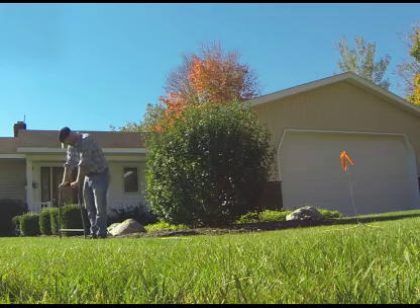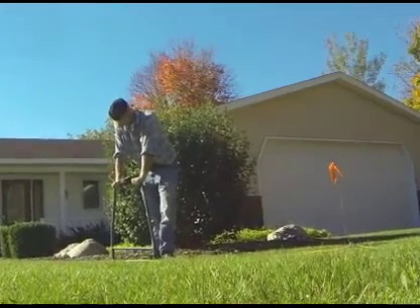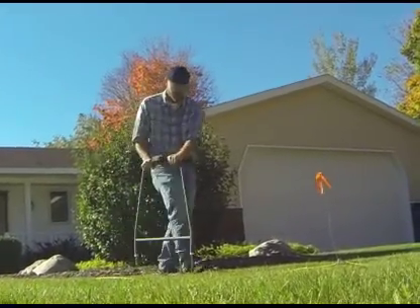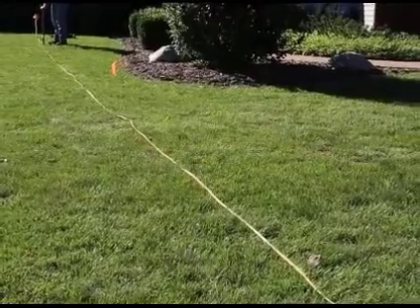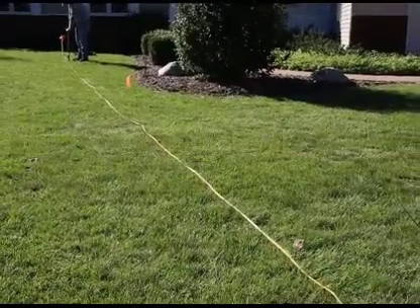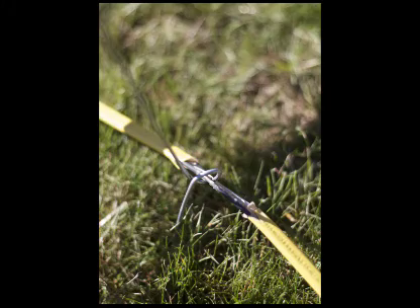The GFL3000 is designed to pinpoint the exact location of a ground fault in a cable. The GFL3000 is not intended to locate the entire path of a cable. To effectively pinpoint the location of a fault using the GFL3000, the path of the cable must be previously determined and the wire must be in direct contact with the earth.